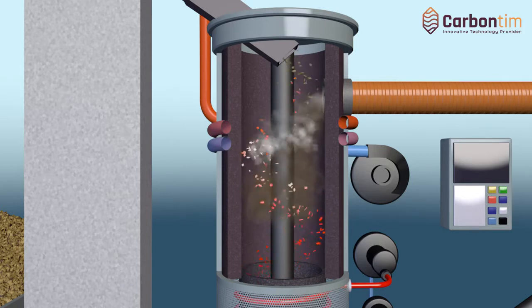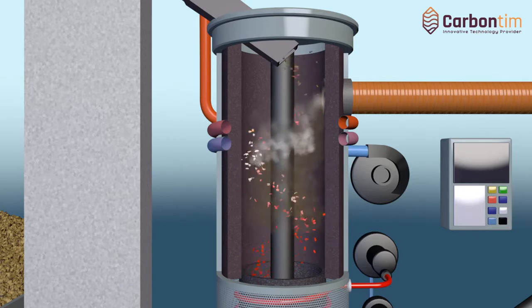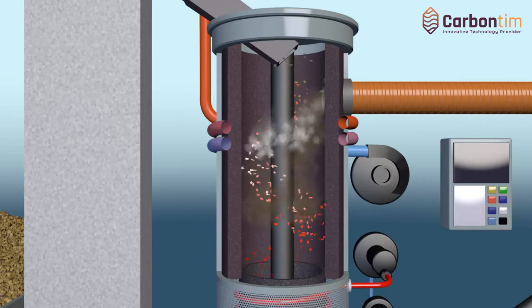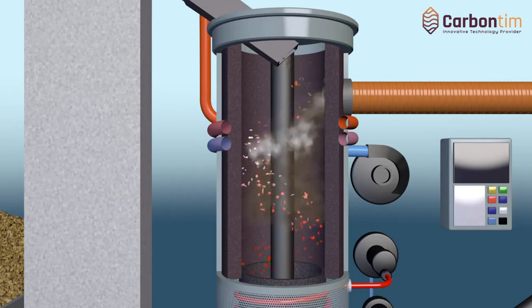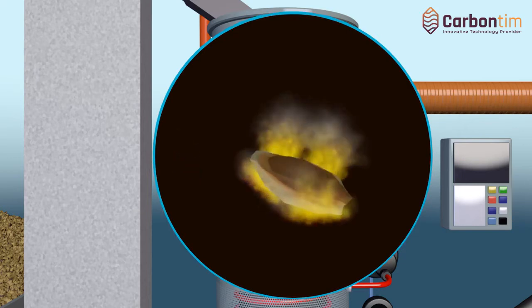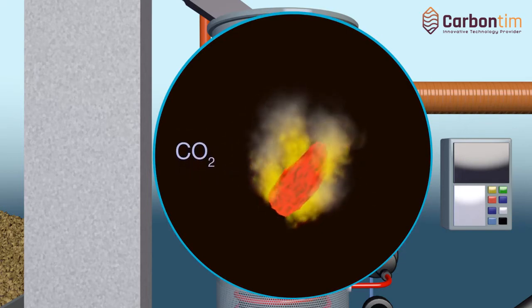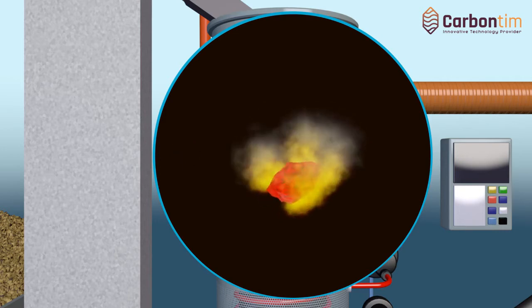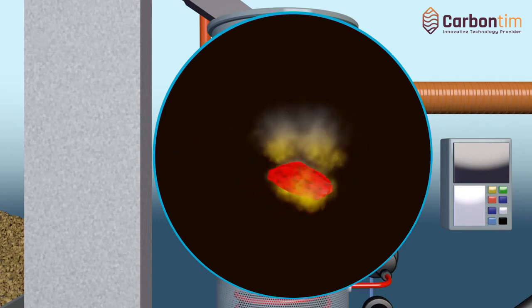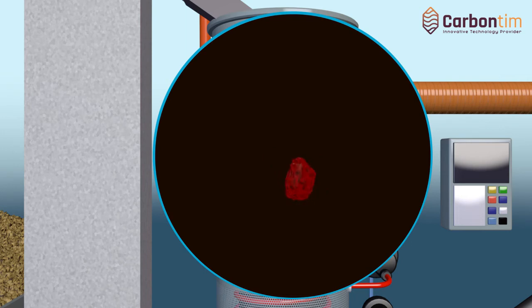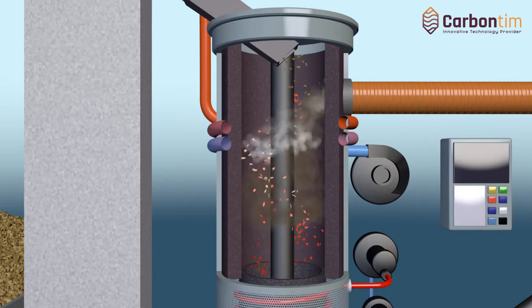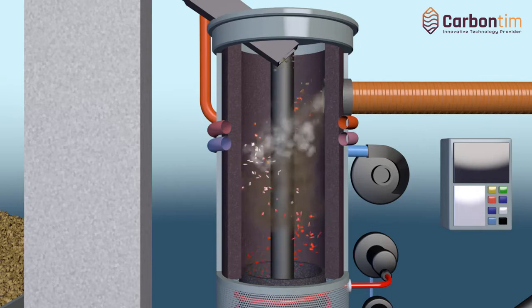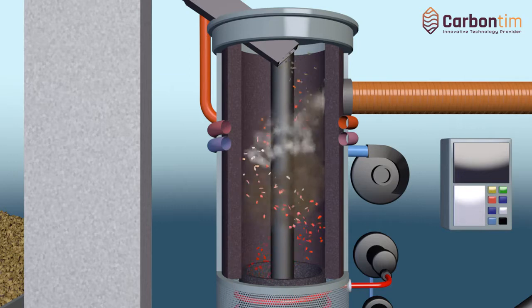The degasification process. In the next stage, the biomass is degasified in the temperature range of 370 to 400 degrees centigrade, within which range the removal of volatile particles is most efficient. Chemical compounds like nitrogen, carbon monoxide, carbon dioxide, hydrogen, and others are flammable, and approximately 40% of the energy yield is consumed by the pyrolysis process. After mixing with the humid air from the preceding process, the remainder of those gases can be used for energy.